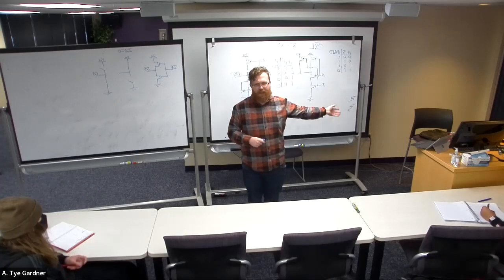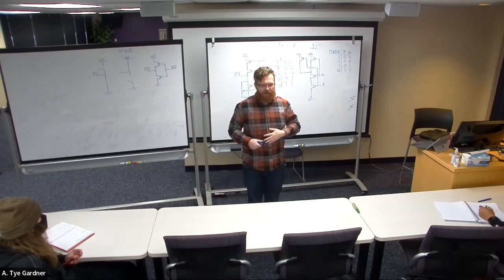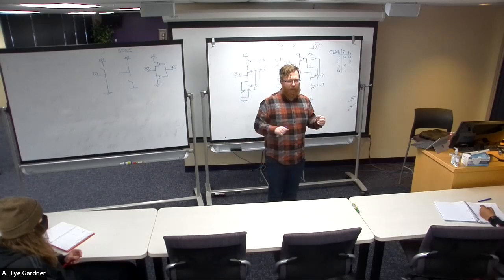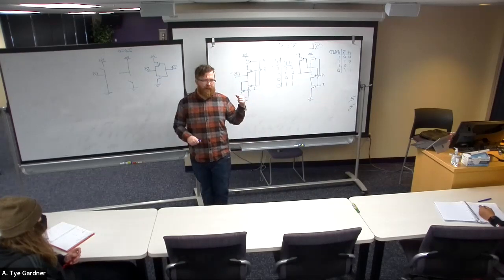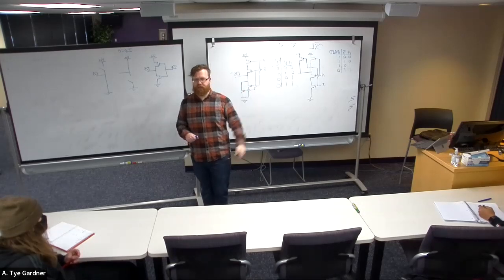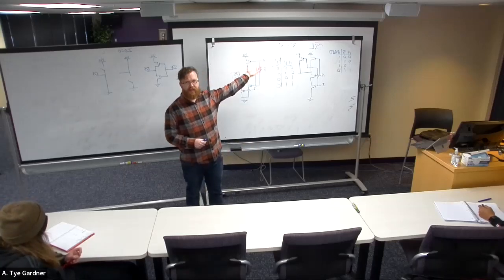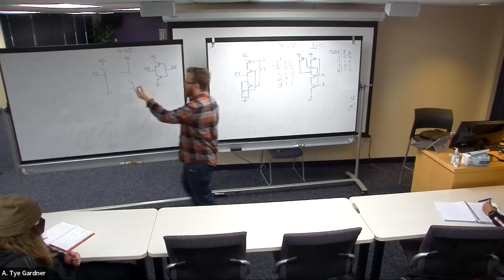the more voltage you need to make them all turn on. And so you have a kind of problem. There's a limit to the number of them that we can stack up. So let's say we could stack 4 of them before we break anything. Well, then that means in order to build an 8-input, I would just do what we did in homework 3, which you definitely all started, right? Which is we can build a 4-input NOR gate or NAND gate or AND gate out of smaller versions of those components. So that's all we would do, is we just start chaining these together and you can get a bigger bit of logic.